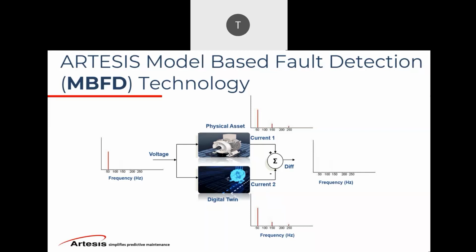Now, down the road, 2 months later, 6 months later, let's say, some of these mechanical components on the motor or driven equipment start to deteriorate. What's going to happen here is that you will see additional harmonics or distortions on the current waveform.